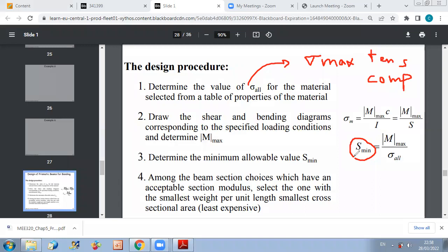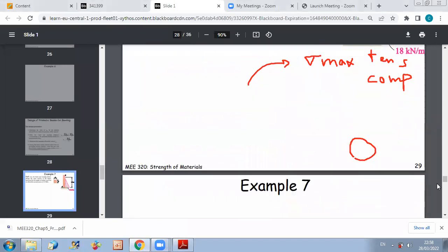And if you remember, when we introduced Appendix C, we said that they gave us an idea about the depth and the value of weight per unit length, in addition to values of inertia, modulus, etc. So now when we do the problems, we'll practice again how to select the corresponding section, which will allow us to not exceed the maximum allowable stresses, and at the same time reduce the cost. Let us continue now with different problems on this chapter.